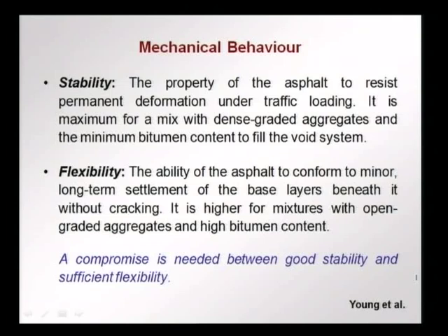This ability to adapt to small settlements of the base layers is important, otherwise it becomes very difficult to have a perfect base layer and not have cracking. This flexibility is now higher for open graded aggregates, that is, there is a lot of space between the aggregates and a high bitumen content, because bitumen is what is giving the flexibility, it is giving the ability of the asphalt concrete to adapt to large deformations.